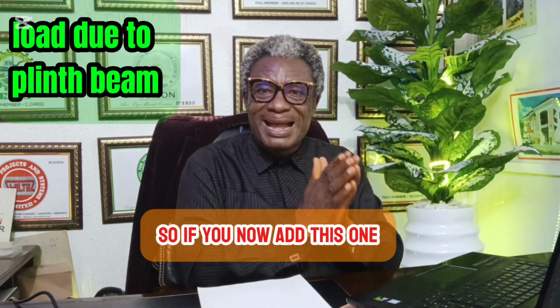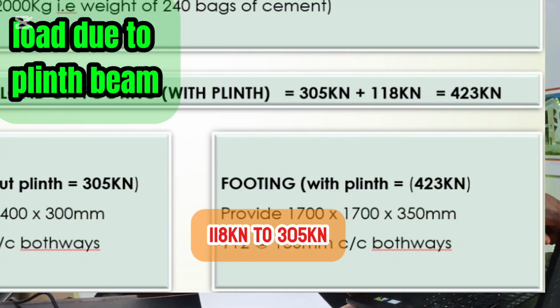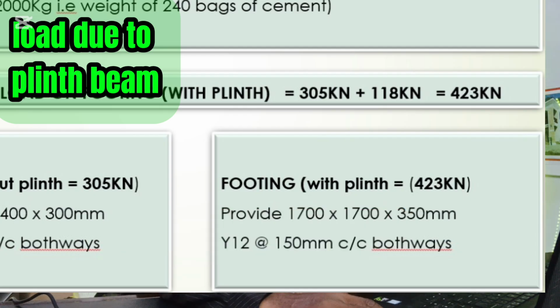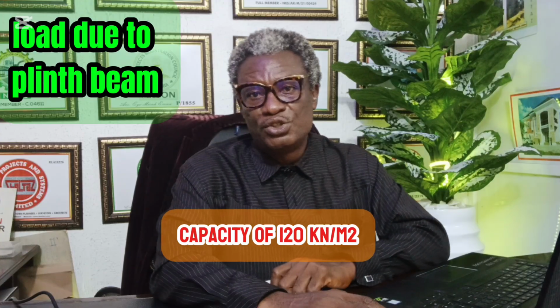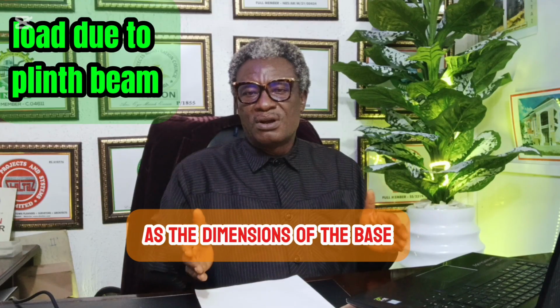So if you now add this 118 kilonewtons to 305 kilonewtons, we're now going to have 423 kilonewtons. Now let's use that 423 kilonewtons to design this same footing using the same bearing capacity of 120 kilonewton per meter squared. So what we're going to have is 1.7 by 1.7 by 0.35 as the dimensions of the base.